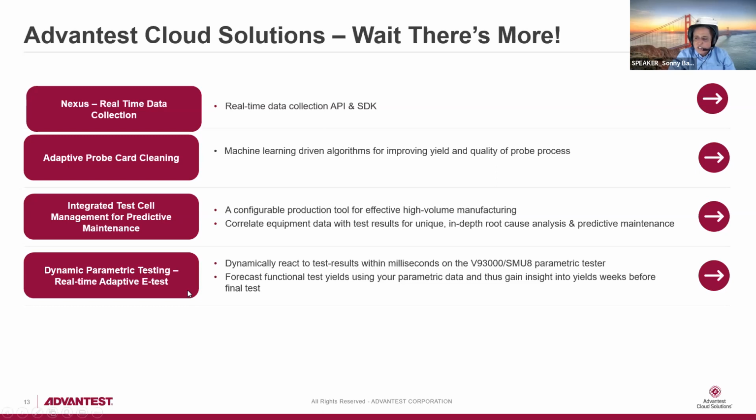And lastly, I just want to talk about parametric testing. A lot of you know e-test, which is the last step in the wafer fab. Now, since this is just a test of the process health of the wafer fab, typically out of the thousands of die on a wafer, only 9 sites are tested. When this data for the 9 sites is sent to the backend, the assembly and test guy at the backend says, "Oh, it's only 9 sites. No wonder I don't know what's going on with my unit."